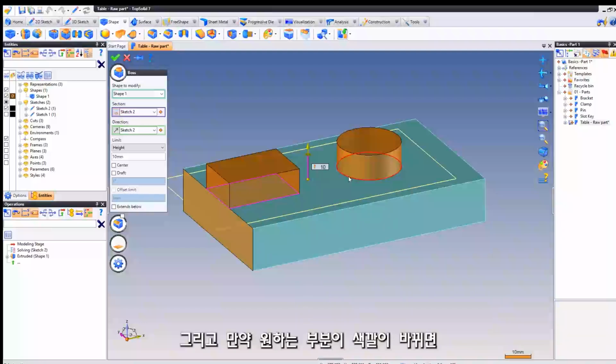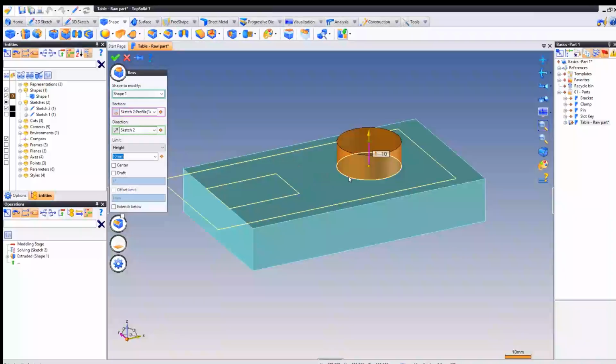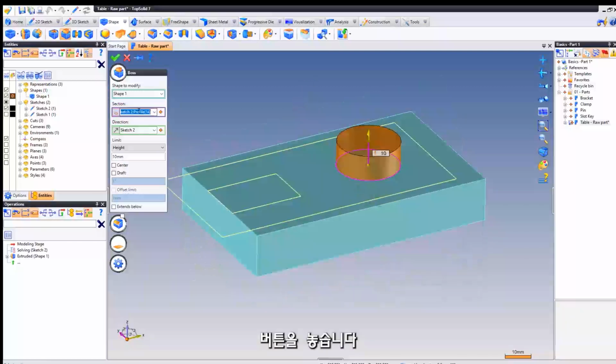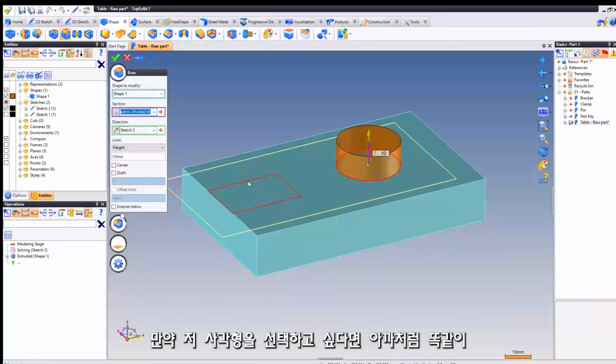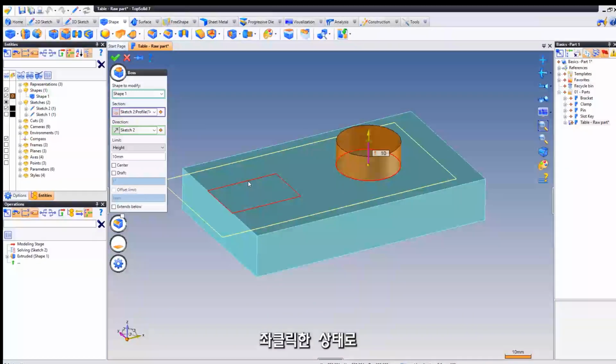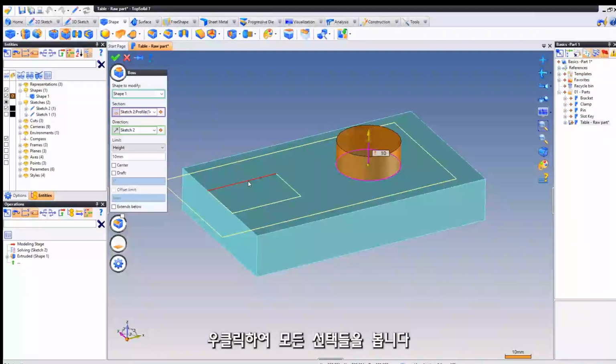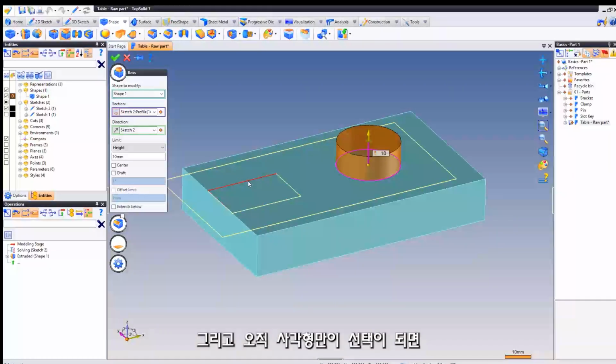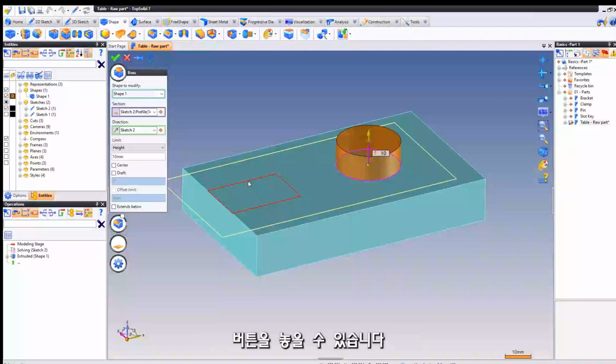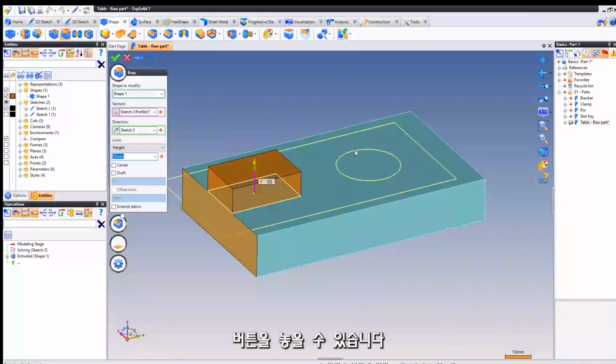And then if the highlight is selected, you can release the button. If you want to get the rectangle, once again place the cursor, hold left click and at the same time right click, successive right click to see all solutions. And then if you see only the rectangle, you can release the button.